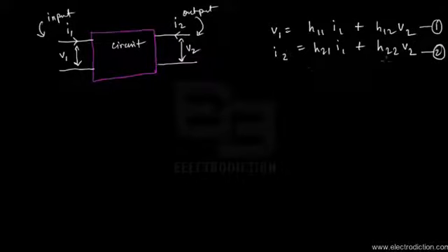Good. Now depending upon this particular method of analysis, we land up with two equations. These two equations, 1 and 2, as you can see on your right, describe the entire behavior of this two-port network whenever we are analyzing this circuit using the H parameter model. You can see over here that only the input current I1 and the output voltage V2 are treated as the independent variables.